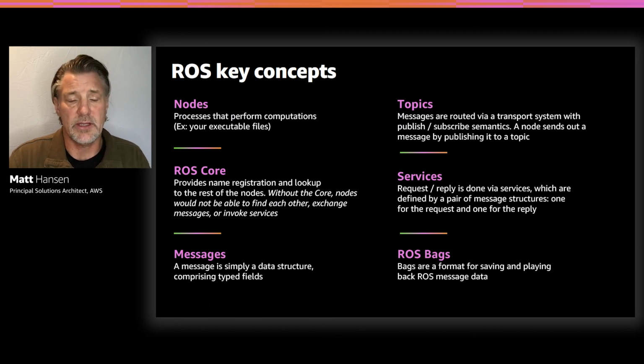They're a client server pattern where you have a node that will make a request to another node and receive a response. And finally, ROS bags are basically a way that you can record and play back data, messages that are being published on topics or services. And this is useful for being able to play back for testing and debug.